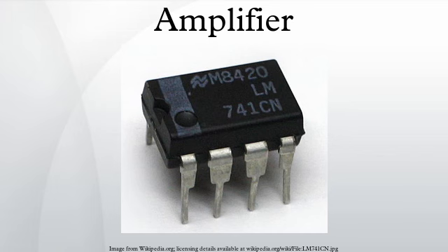These functional descriptions usually apply to complete amplifier systems or subsystems and rarely to individual stages. A servo amplifier indicates an integrated feedback loop to actively control the output at some desired level. A DC servo indicates use at frequencies down to DC levels, where the rapid fluctuations of an audio or RF signal do not occur. These are often used in mechanical actuators, or devices such as DC motors that must maintain a constant speed or torque. An AC servo amp can do this for some AC motors.